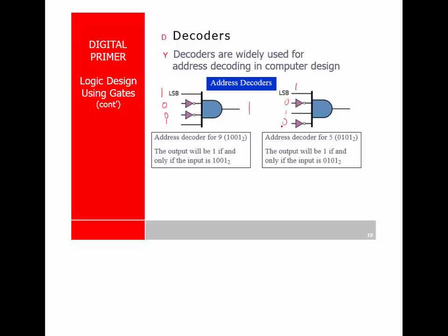They're used a lot. Now, again, typically we don't use them with just a single NAND gate, but we could use them with a single NAND gate right there. Usually when we look at the chip, this is actually built into our address decoders or our memory devices. We can use some of those for the decoder.